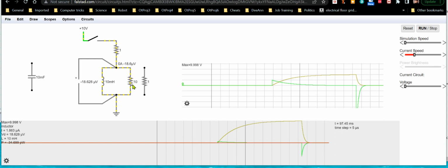Again, even if it's low current, high voltage, like from a flyback transformer on a TV, you can burn out a standard resistor, and its resistance will basically be zero afterwards. I've even blown out some fairly high voltage resistors that way. Not using this, but I mean like flyback transformers and stuff like that. But resistors do have voltage limits on them. You've got to buy special high voltage resistors, like from Mouser or DigiKey. They're not too terribly expensive, but you still have to think about that.